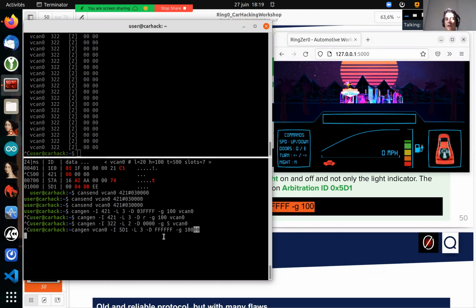This is the surrounding light information. And when we tell our BCM that there is light, it's the day, so you can shut the light off, then we have an effect and we are driving by night without any light at all. And this is dangerous. So we saw two differences between the indicators and the real status, the control of the light.